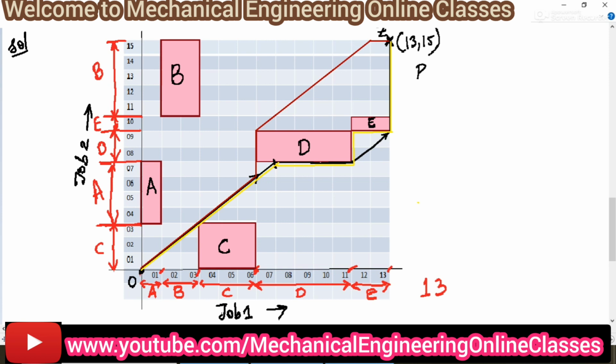So if we are choosing the red path, let us see what is the total time. From 0,0 to this particular point, it is 6 hours. So within 6 hours, job 1 has completed going to machines A, B and C. Job 2 also completed C, A. Till this point it is 6 hours, plus from this point to this point, this length of the line is again 3 hours, from 6 to 9.